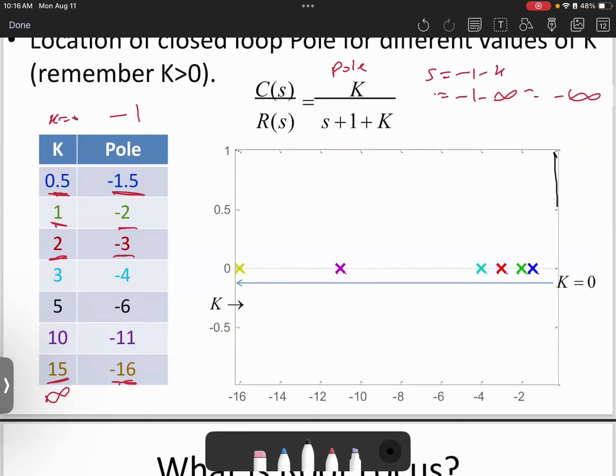So as a result, if we need to plot them, we can use the s-plane, which is the same thing that we used to do in pole-zero mapping. Basically, the original pole, or the open loop pole, before doing the closed loop, was located at -1. So here is the j omega axis.